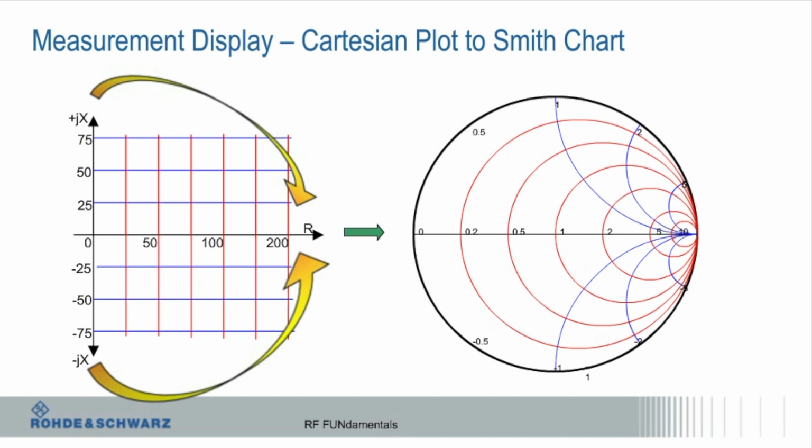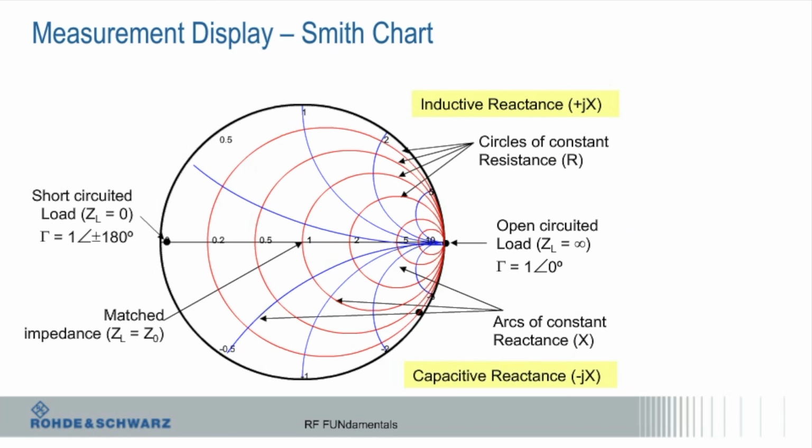You can use the Smith chart to get from one impedance to another. And it'll tell you what length of line you need, what complex impedance, what real impedance. Okay? If you look on here, this is what you've got to know about a Smith chart.